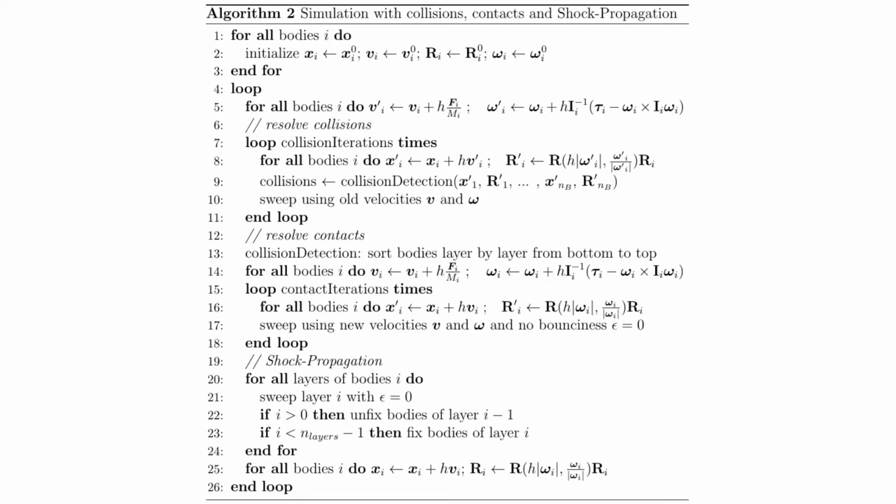Now, I won't go too much into detail about how to construct this global matrix, but it's a sparse symmetric matrix which can be solved with Cholesky factorization, and doing this will only require few iterations and also be not as sensitive to large mass ratios, and also the order of constraints doesn't really matter. So there are ways around this, but these methods have other drawbacks again.